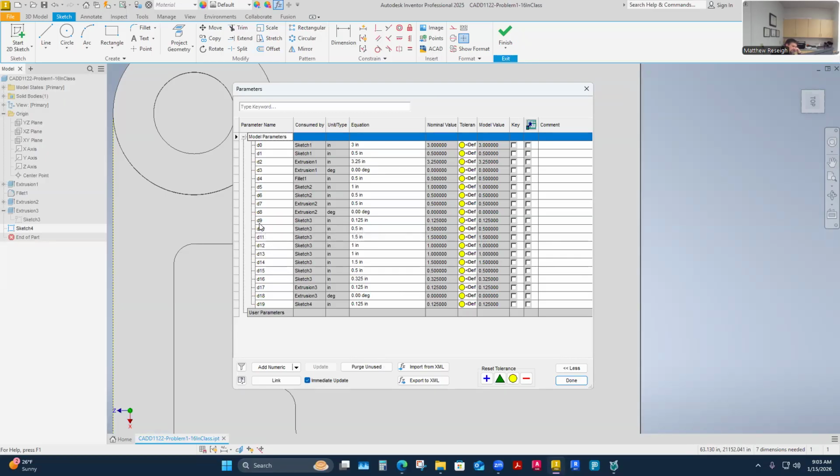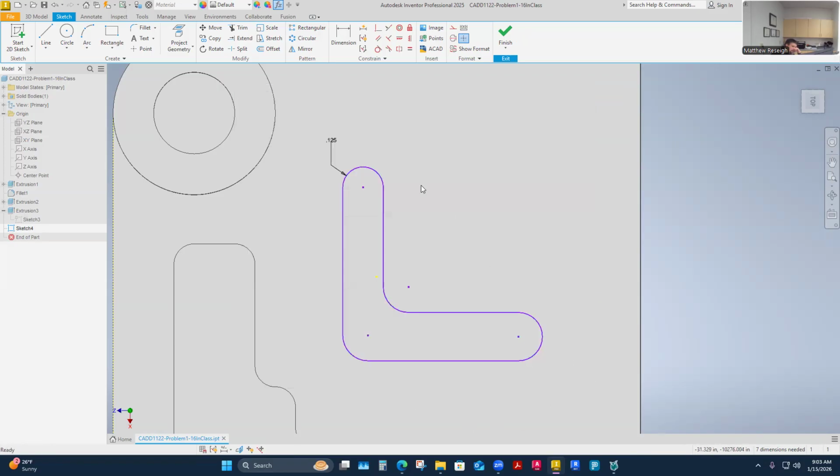I can actually type in D9. I'll just show you here. You don't have to do this. I just like to show some things that maybe aren't always in the book. If I click in here, you can also use a little lowercase d, D9. It will accept this as a dimension because it's in my table. And there it is, an f of x D9. Now if I went into sketch 3 and changed dimension 9 there, it would change over here too. That's a parametric concept, but I minimize data inputs and maximize output, maybe.